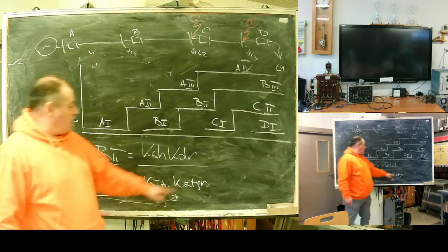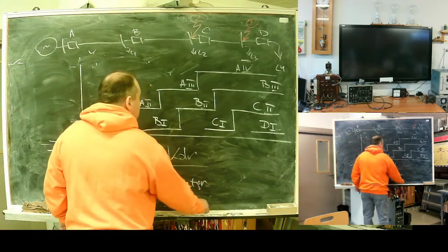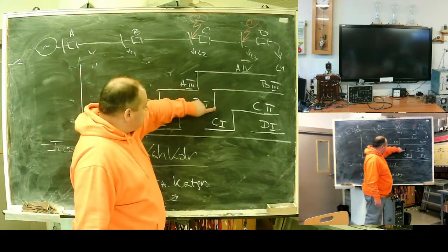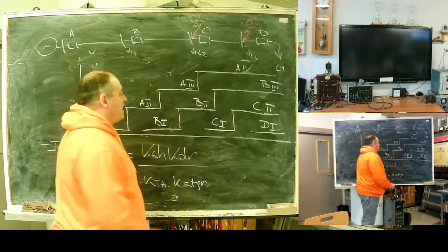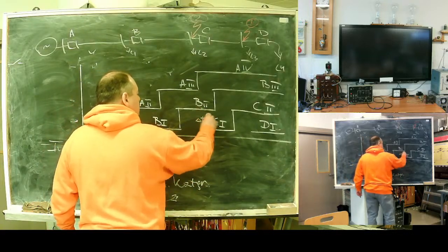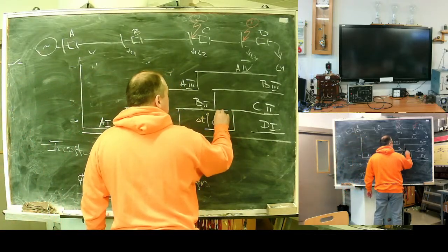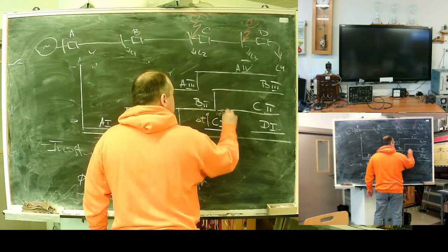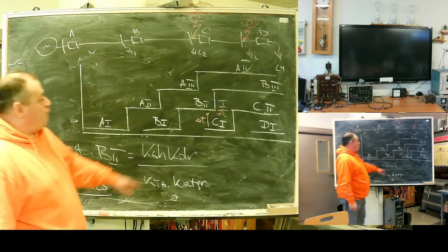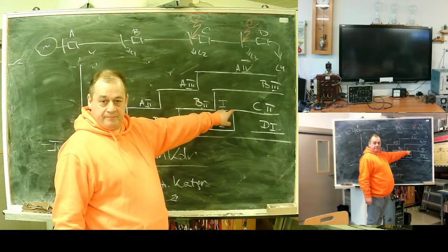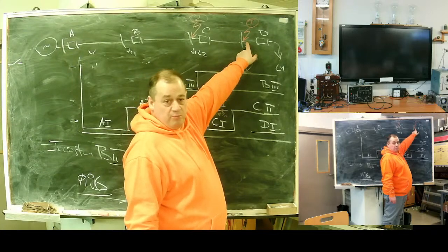And what should I write here? They should understand. I need, you see, I need this gap. In this direction, it's delta t, in time. Here it should be 10% in current. Understand? What defines this point? Trip current of C1, and it's calculated from point 1. Yes?